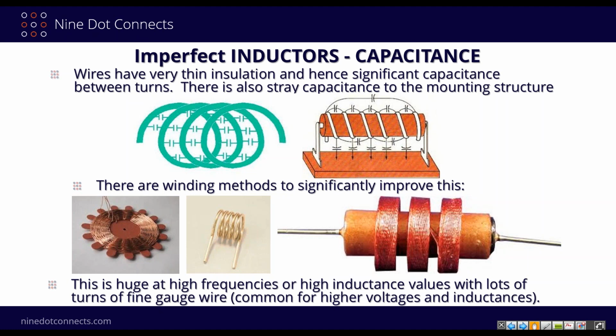Second, the one in the middle is just a regular simple coil, but it's been stretched apart so that there's an air gap between all the turns. That decreases the inductance. Similarly, the one on the left is a plate type winding, a flat type winding, planar winding, but it uses an odd number of little things that stick out, sort of like tongue depressors, and they weave in and out between there. Since there's an odd number each layer, the wires are crossing. There's none that are laying parallel to each other, at least not on adjacent turns, and as a result, the self-resonant frequency goes way up because the inductance goes down.